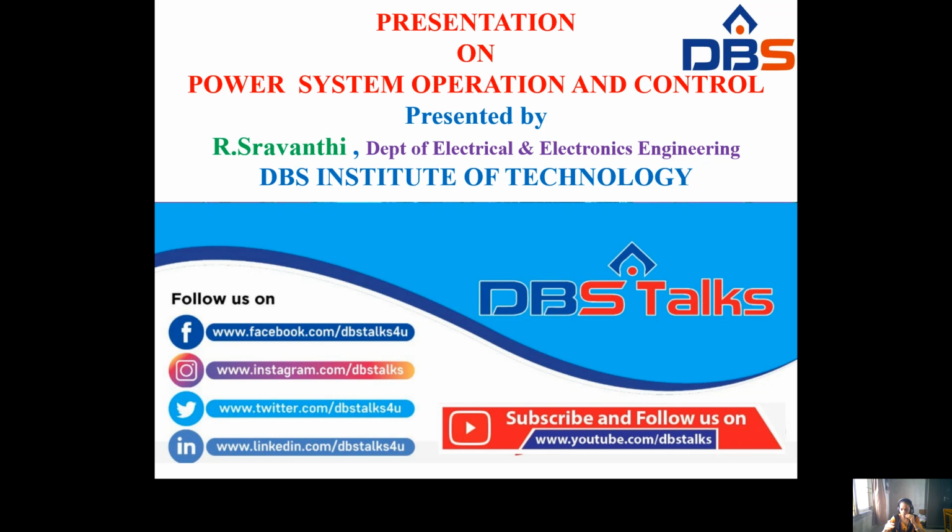So the frequency and power are directly proportional, and they are also directly proportional to speed. Whenever the speed changes, the frequency also changes, because Ns equals 120 f by P. Here we want to maintain the frequency constant, so by using the speed governing system, we have to maintain the frequency constant.